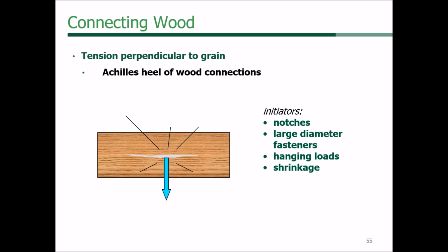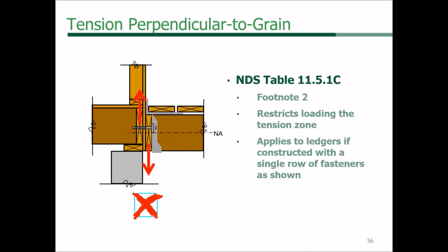I was chopping some wood for a fire pit yesterday, and I was thinking about how the hatchet was going in, and it was literally just causing tension perpendicular to grain failures. That's one of the reasons why a lot of decks failed: either because of tension perpendicular to grain, because they didn't stagger those bolts, or they were using nails in it or something like that, and with the wet surface, it just did not have much withdrawal strength and it just fell.